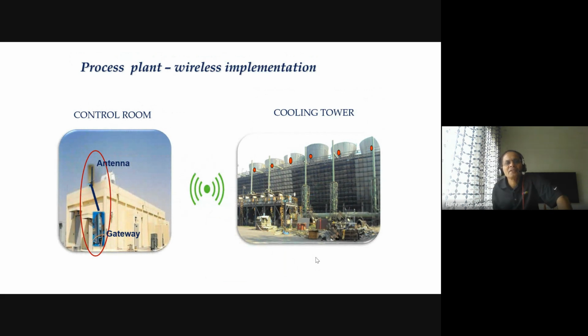So in the plant, you can see here the transmitters are red dots, wireless transmitters, and inside them sensors are connected, and these are directly connected to this antenna. If wireless is not there, then you can just imagine how you would have to take the cables from here, dig the road, carry them up to the control room this side and connect it. So it's a big job. Now you only install it here and the signal comes to this antenna here.